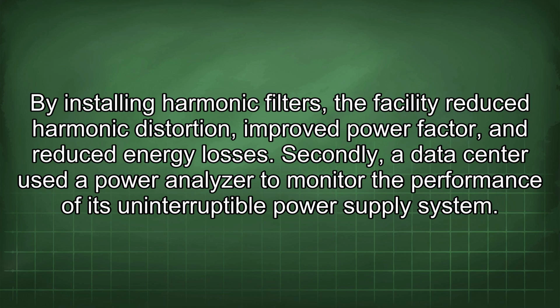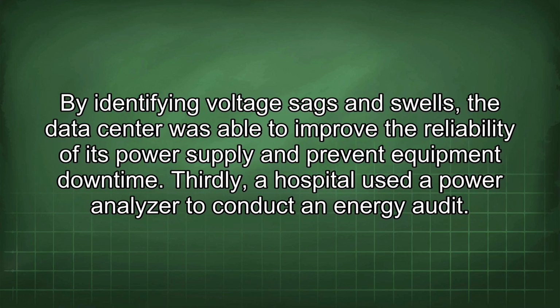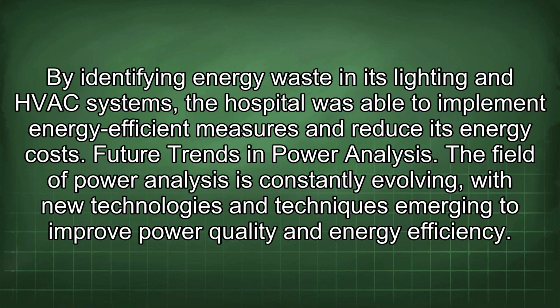Secondly, a data center used a power analyzer to monitor the performance of its uninterruptible power supply system. By identifying voltage sags and swells, the data center was able to improve the reliability of its power supply and prevent equipment downtime. Thirdly, a hospital used a power analyzer to conduct an energy audit. By identifying energy waste in its lighting and HVAC systems, the hospital was able to implement energy-efficient measures and reduce its energy costs. Future trends in power analysis.